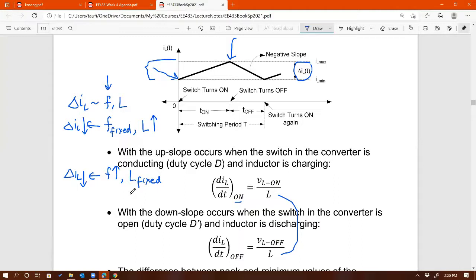You got it. So from switching losses, right? So when you are using PWM, then the loss equation for PWM is going to be proportional to f, right? So the higher the switching frequency, the higher the switching loss, right? So in E411, we talked about ways to reduce switching losses, right?